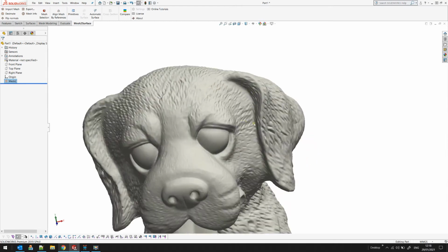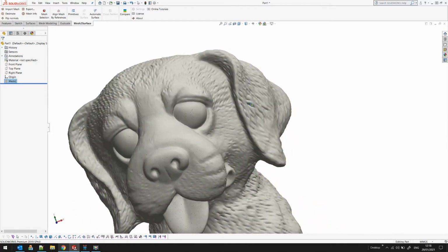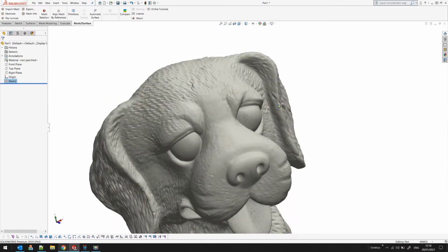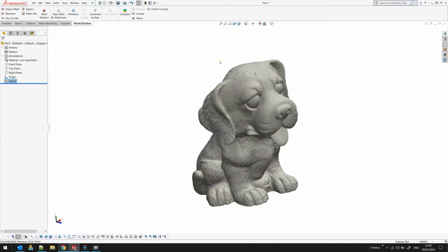The whole idea behind this is that if the number of triangles is more than 1 million, the software automatically turns the visualization into point mode, which is easier to render on the screen. But despite this, for the algorithms, this might be quite a lot of triangles. You can continue and do your reverse engineering on this mesh, but in some cases you may want to reduce the number of polygons that we have in this mesh for easier manipulation. For this purpose, we have a function which is called decimate.